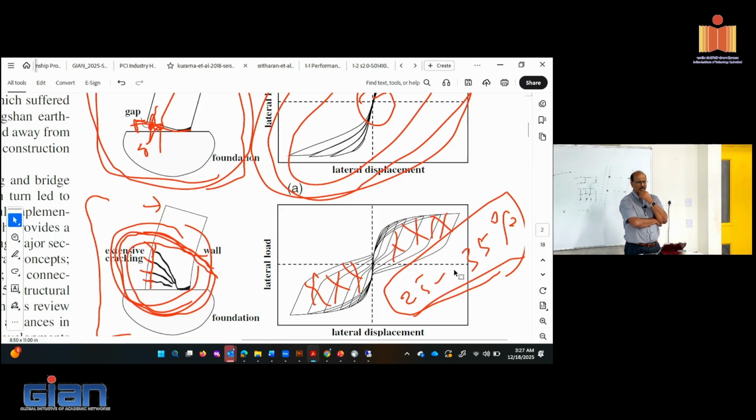I think it's a program called the SAC project. They reinvented how they should design structures for seismic. At the end of that program, they saw what precasters have done, and they actually took the hybrid connection and applied it to steel structures as well. And they have also built some structures with post-tensioning, which surprised me, to hold steel structures together. So the hybrid concept has gone quite a way.